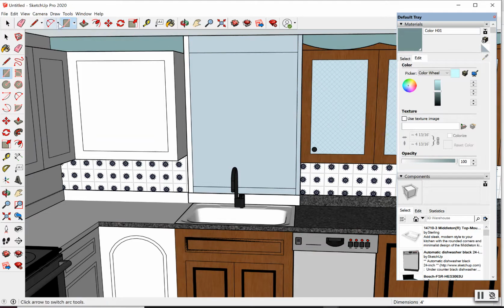From here, I'm going to draw a line. We already have a trim that was created for us on our AutoCAD drawing, but I also want to trim the window out a little more, but I'm going to bring my trim down, which then will make my window 3 feet almost. So I'm going to bring my trim down at least 1/2 inch from the top and the bottom. So typing in 1/2 inch.